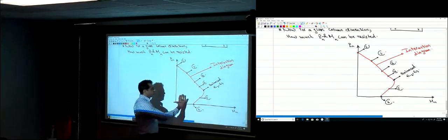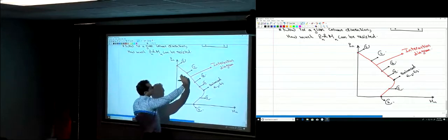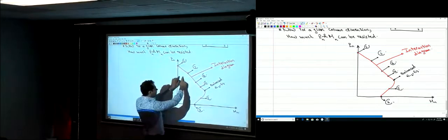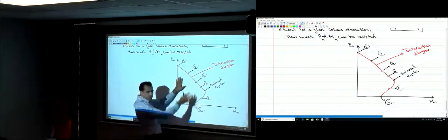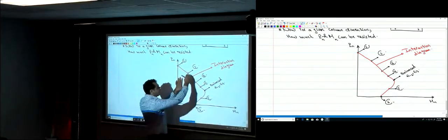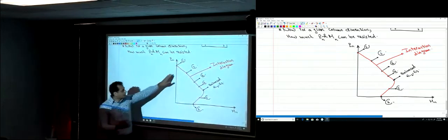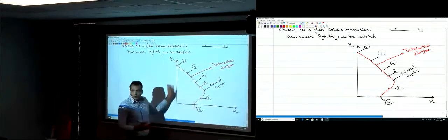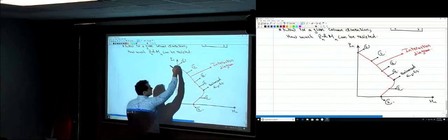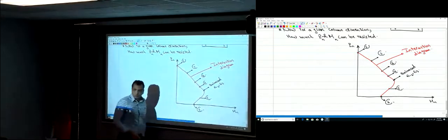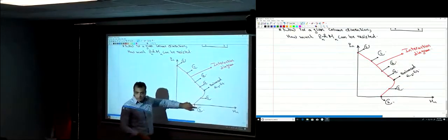You can be within that curve. If you have a P and M over here, the column can resist them because it's within the limitation of that curve. But if you're outside that curve, the column will fail. As long as you're inside that curve, you're good, and failure will not happen. Failure will happen when you reach that curve; those points are at failure.